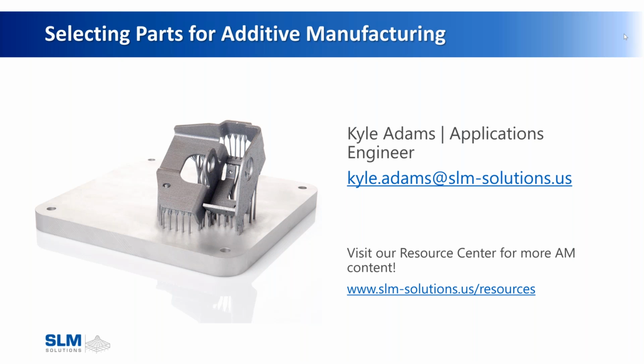Gotcha. Okay. And FDM is not welding. It's bonding together. Even in a metal FDM process, you're bonding together stuff using an adhesive and then baking it together. So there's a lot of layer lines and there's fault lines. Where it's welding, every time we weld multiple layers deep. So we're creating much stronger grain structure and much more closely related to what real cast or forged metal would be. Right. So it's stronger. Is it more consistent throughout the part as well? Less variability in mechanical properties?